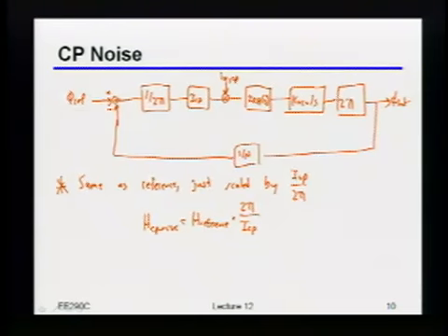Okay, so that's pretty easy. And again, the main point there is that you can't build the lowest power charge pump in the world, because if you do, it'll have enough noise current that it could actually end up dominating your overall jitter characteristics. Okay, so now let's see what happens if we add some noise into the loop filter.